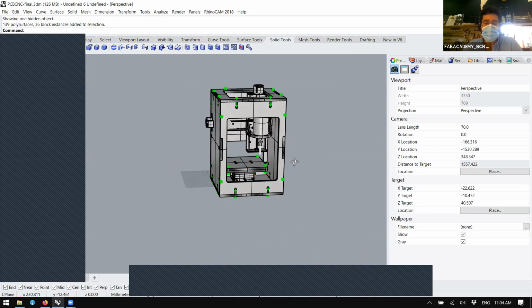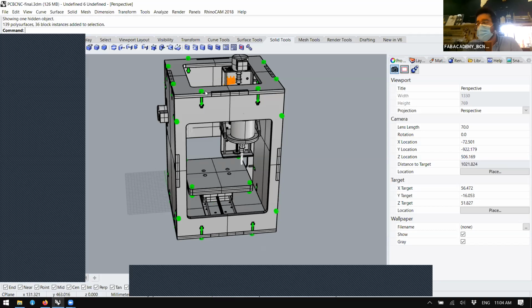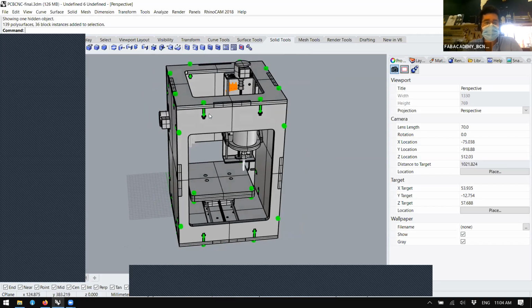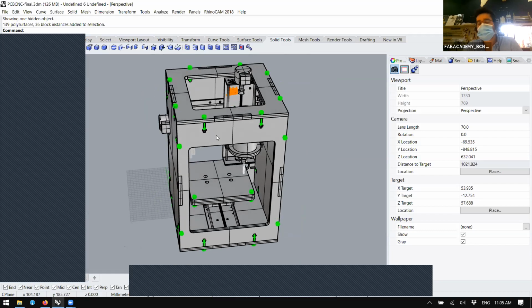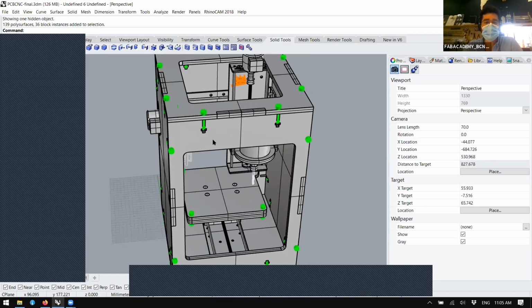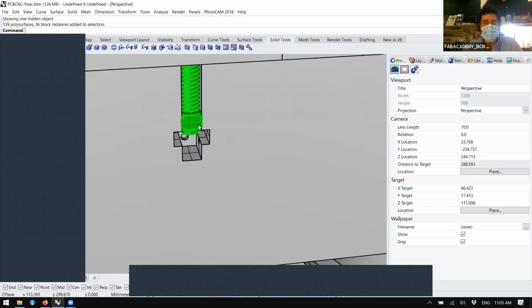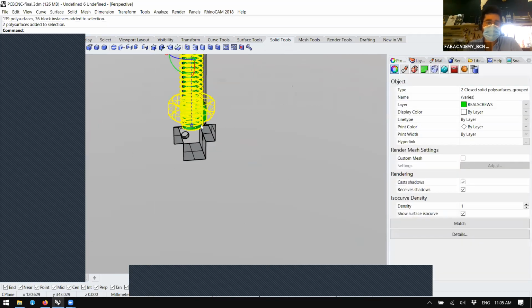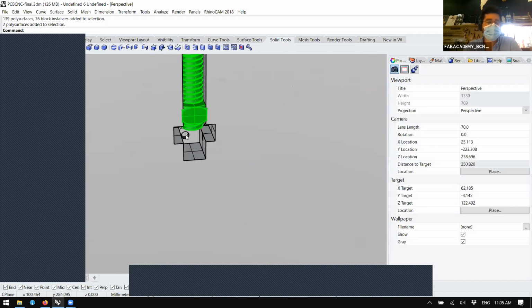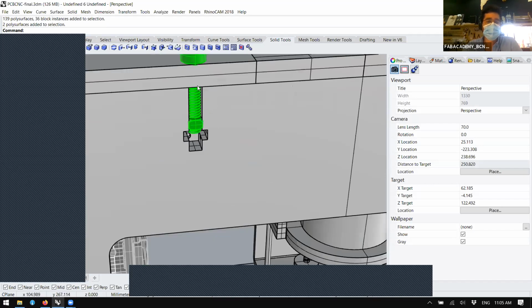Right now, the machine is made out of acrylic, and a good way to fix acrylic parts without using glue, which is something you always want to avoid, is, for example, using this kind of joinery. It's a 3D model, so I didn't put the nut correctly, but this nut is supposed to be here, and you screw through it.